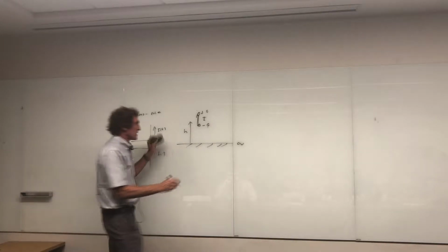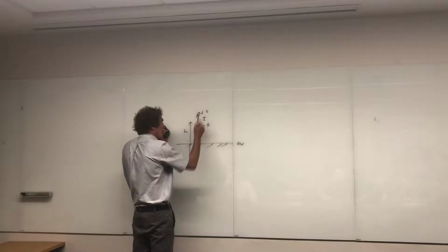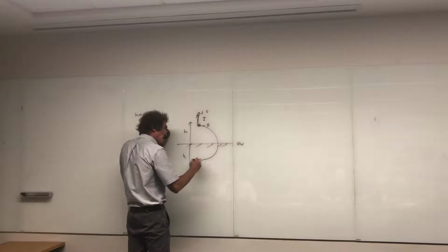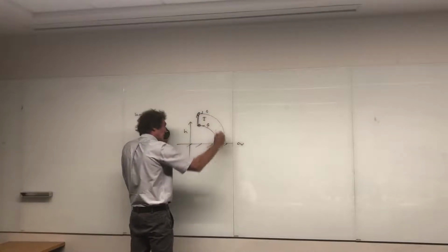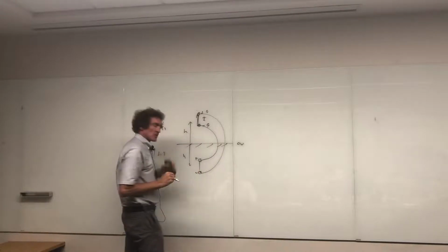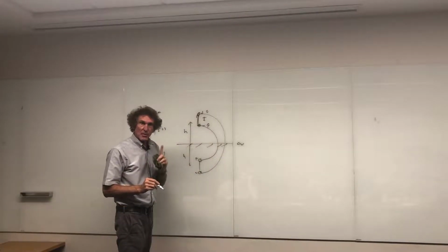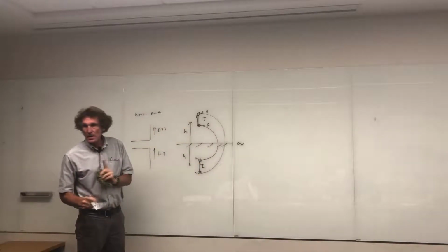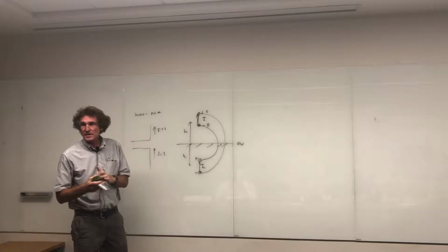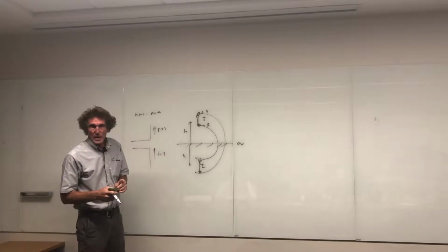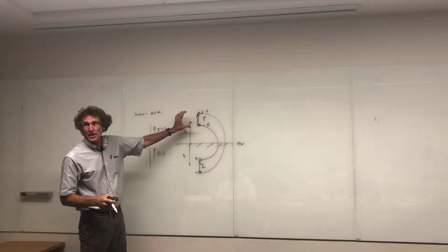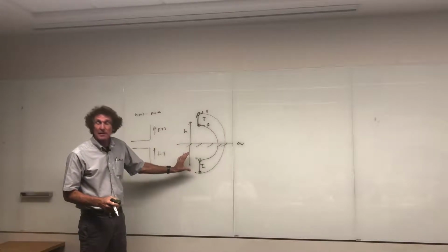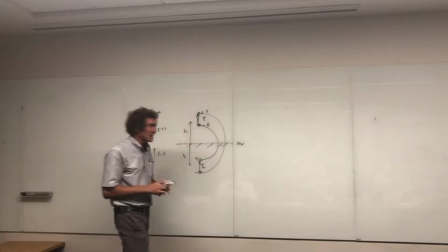Now just do imaging. Come down here at a distance h. Now I'm going to have that same image thing, but where there's negative charge there, there's positive charge here. Where there's positive charge here, there's negative charge there, right? Now, which way would a current have to flow to create that? You all see it flows this way? Everybody see that? What that tells us is this: we can take any current that's vertical, and simply take the image of that current beneath it and literally double the length of a monopole, effectively making it a dipole.